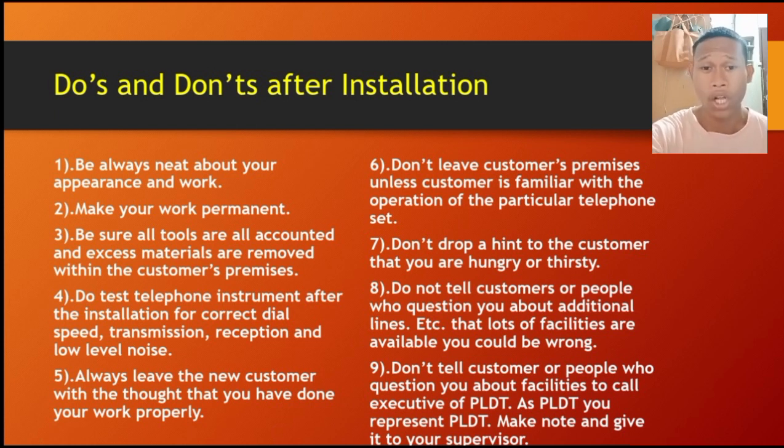First is be always neat about your appearance and work. Second, make your work permanent. And the third, be sure all tools are accounted for and excess materials are removed within the customer premises. Fourth is do test telephone instrument after the installation for correct dial speed, transmission, reception, and low-level noise. Fifth, always leave the new customer with the thought that you have done your work properly.